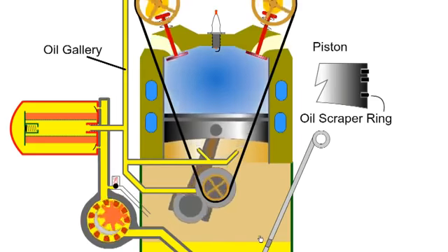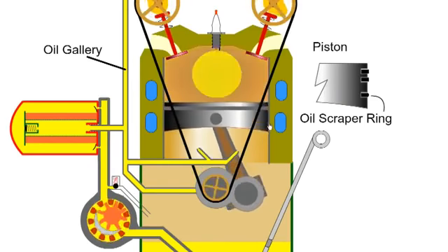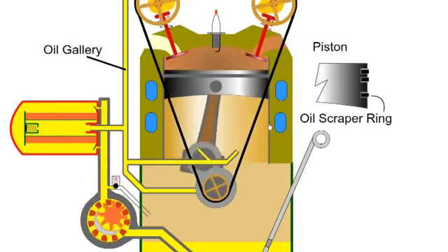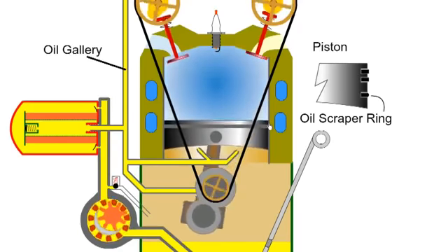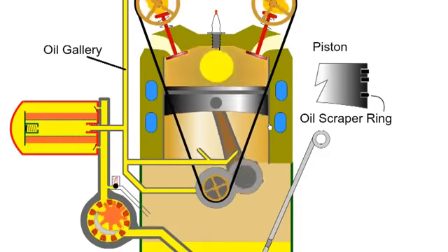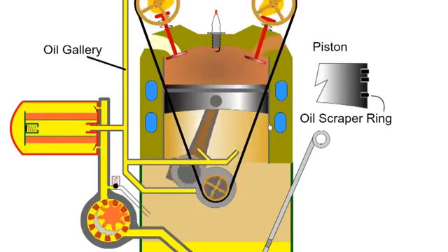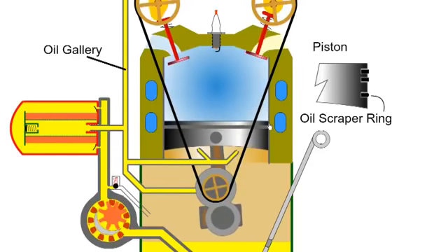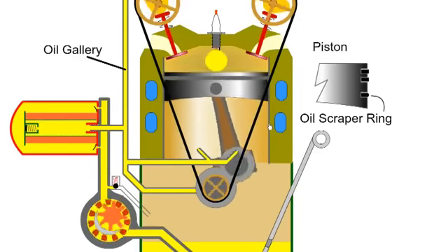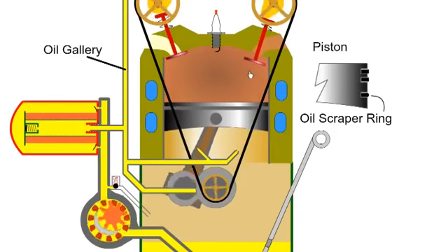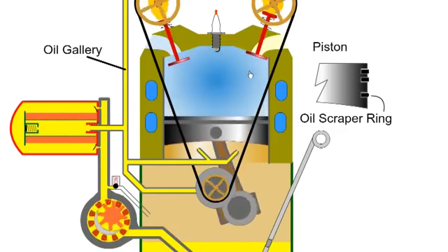The oil will provide a sliding seal between the piston ring and the cylinder wall. The seal helps maintain cylinder compression during the compression and combustion cycle, preventing blow-by. It will also prevent oil entering the combustion area when the cylinder is under negative pressure during the intake stroke.